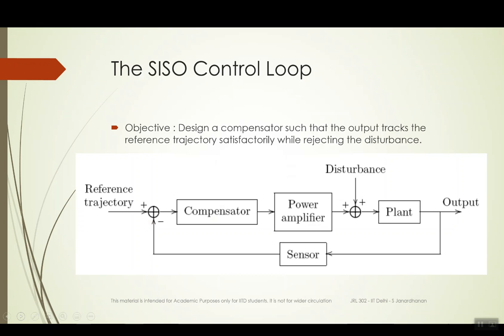Okay, and this brings that to the objective. So now what you have is the plant is almost linear. Okay, the linear plant, this is your actuator, and this is the compensator that you have to design. So you have a reference trajectory theta d, which is a constant in this case. This entire picture works well even if the reference trajectory was not a constant, but let us consider the constant. And the output is this theta that you have, and the input is this theta z.